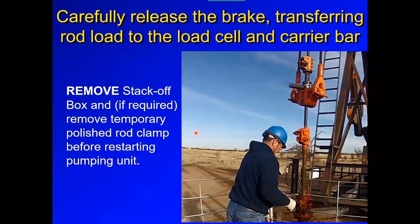Now, once you've installed the horseshoe load cell transducer, okay, and the area is clear, you're going to carefully release the brake, transferring the rod load back onto the load cell into the carrier bar. Now the load cell is measuring the rod load. Okay, we'll remove the stack off tool and place it off to the side.